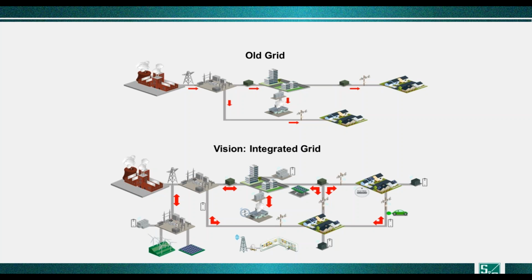That creates a really interesting dynamic, and not a good one. There are a couple of things this creates, and that's the opportunity for what I'd like to call blinks: very short durations of no power. That's bad for PV, because the smart inverters, with a momentary outage, will lock out for 5 minutes. And we'll go through that consumers today are seeing blinks as the major irritant of the grid. And quite often we're not even measuring it.